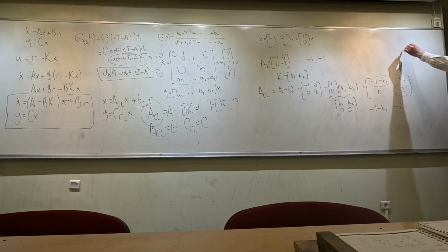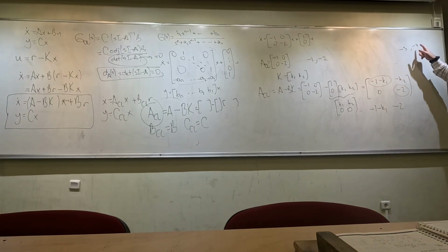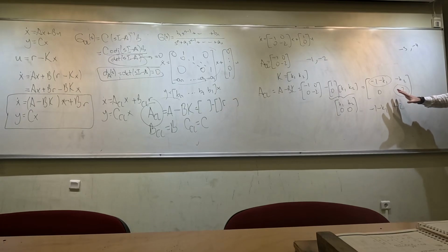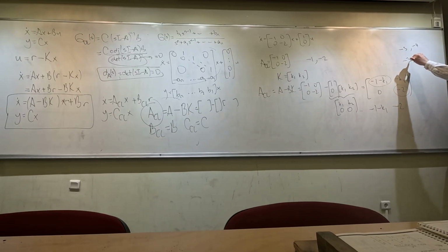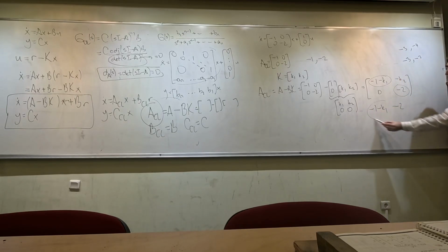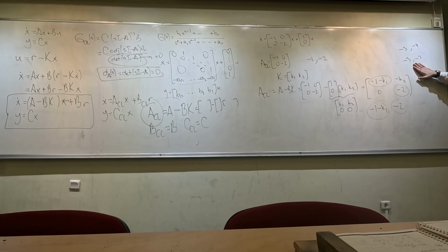Okay? So do you think I can bring the poles of this open loop system to -3 and -4? Can I bring the open loop poles to these closed loop poles? So we see that sometimes we cannot do this. By choosing any K, we will not be able to do this actually. Can I bring the pole locations to -3 and -2? Yes, I can just bring this to -3 and then to -2. So some pole locations are still allowed for me, but some pole locations are inaccessible. Okay? I will not be able to do it using any K.